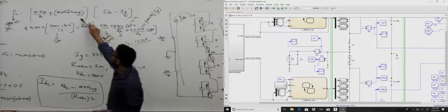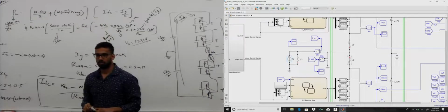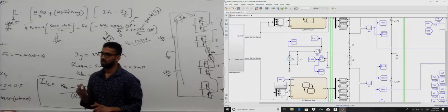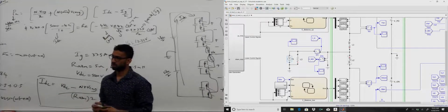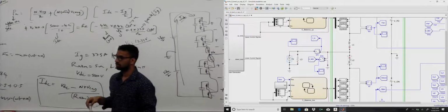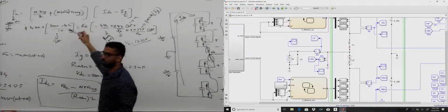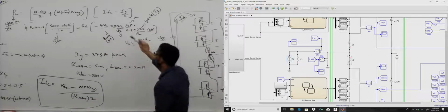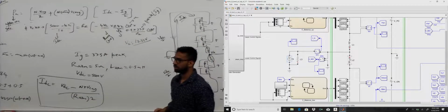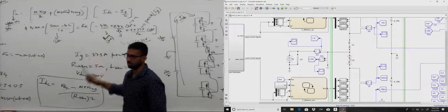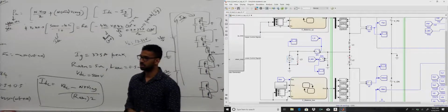And we used this equation to find out the origin of the second harmonic current last time. That assumed we did not know that there was a second harmonic circulating current to start with, and then the second harmonic circulating current resulted due to this basic power equation. So in these calculations I only assume that the circulating current consists of IDC, and that is sufficient to find out DC power because other components don't contribute to DC power.